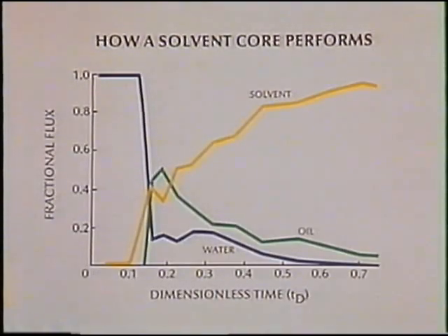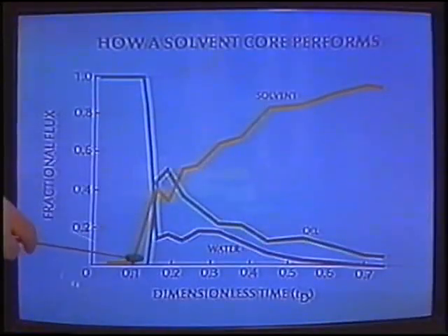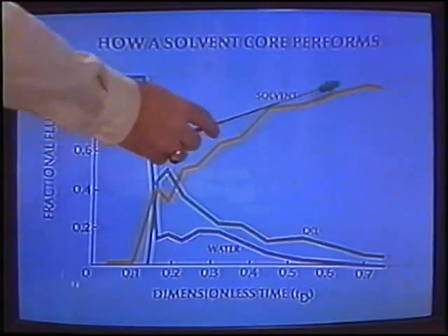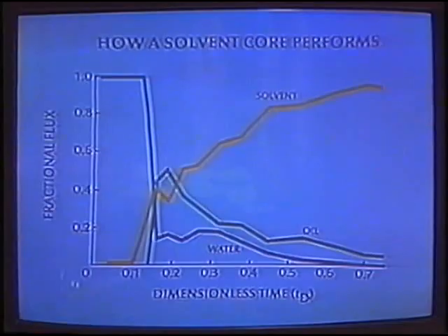Now, it's a tertiary flood, and the solvent, in this case CO2, did in fact develop miscibility with the oil. But remember in micellar flooding how we said in a core flood the micellar solution banked up the oil and produced a large fraction ahead of the surfactant as clean oil. Such does not happen even in a core flood here. In fact, the solvent is a little bit ahead of the oil, and rather than a displacement, you might fairly characterize this process as a sort of dragging. The oil is literally being dragged out of the core rather than being pushed out of the core. So there's a long simultaneous production of solvent and oil, and the oil peaks very rapidly and tapers off rather gradually. Why are they breaking through together?